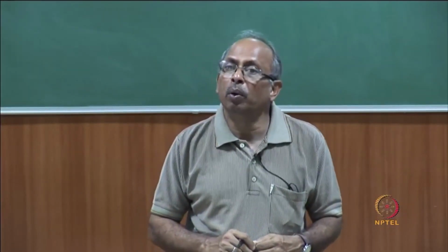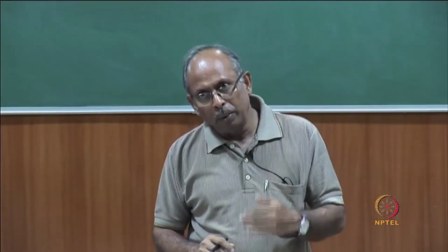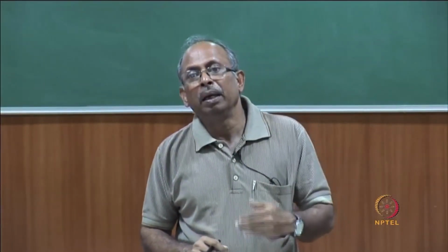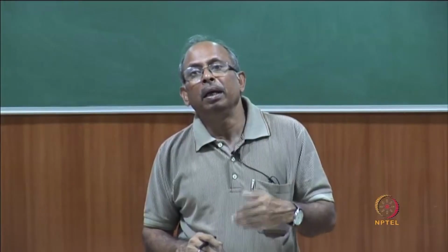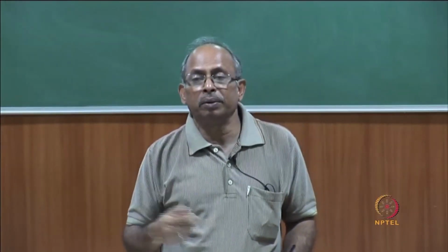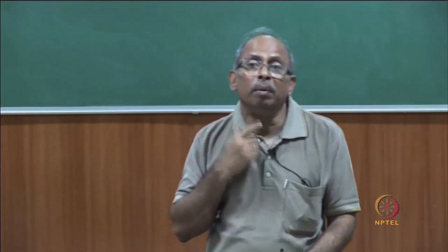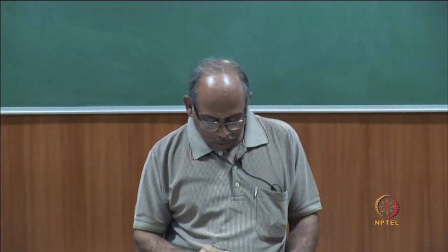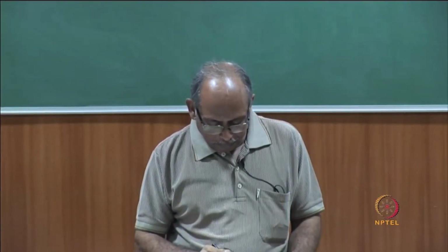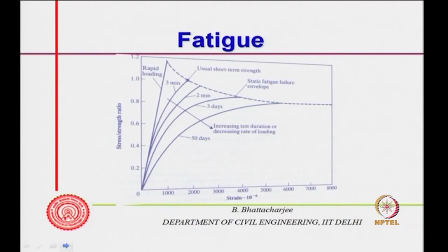Repeated cyclic loading is of course the other case, where you are operating at a much lower level, but then it fails because repeatedly you have done reversal of stresses over a large number of cycles. So, these are the two situations, and we can see the behavior in this manner.